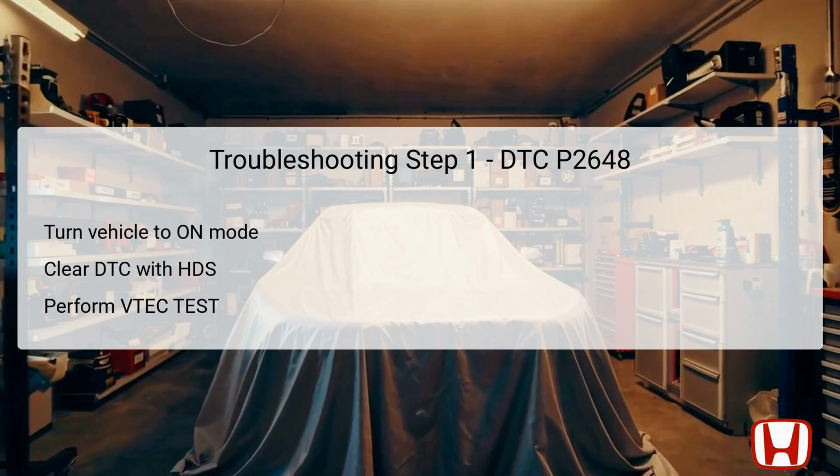After clearing the code, perform the VTEC test found in the inspection menu of the HDS. This test checks the functionality of the VTEC system, crucial for evaluating the rocker arm oil control solenoid function. Finally, use the HDS to check for any pending or confirmed DTCs that may present themselves again. This step helps determine if the issue is persistent, indicating a failure, or intermittent, which requires further investigation.